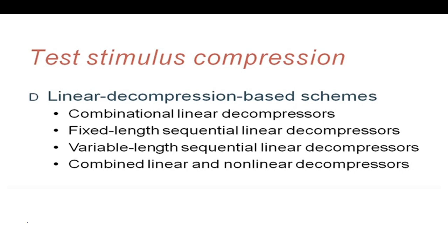Test stimulus compression. So linear compression based schemes. This is for the test stimulus. Combinational linear, the second method. Combinational linear decompressor or fixed length sequential linear decompressor, variable length sequential linear decompressor, combinational linear and non-linear decompressors.